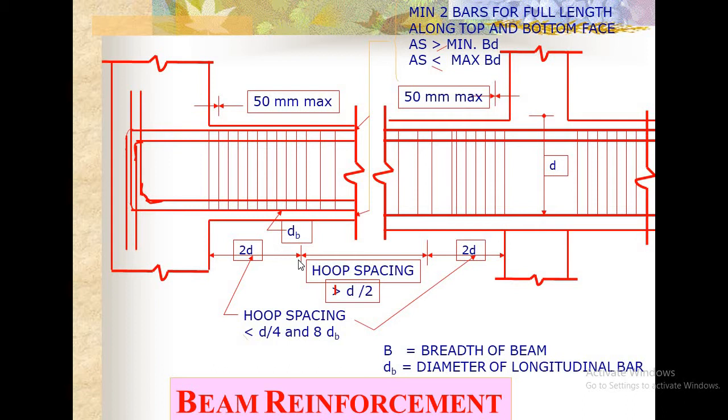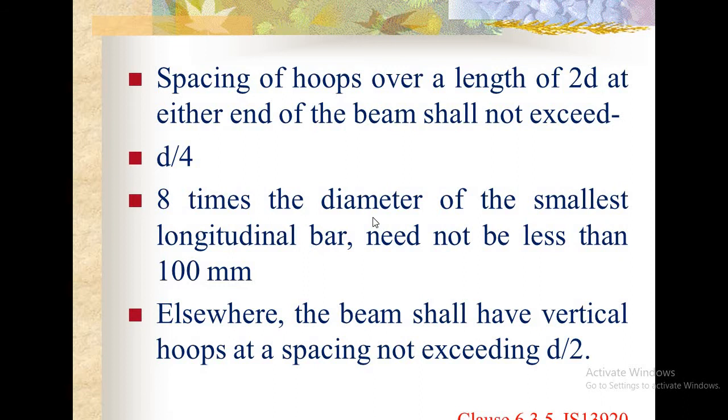The shear reinforcement has to be provided in such a way that within this 2D length, the spacing should be minimum, because of the need to resist maximum shear stress. Also, 8 times the diameter of the smallest longitudinal bar, need not be less than 100 mm.